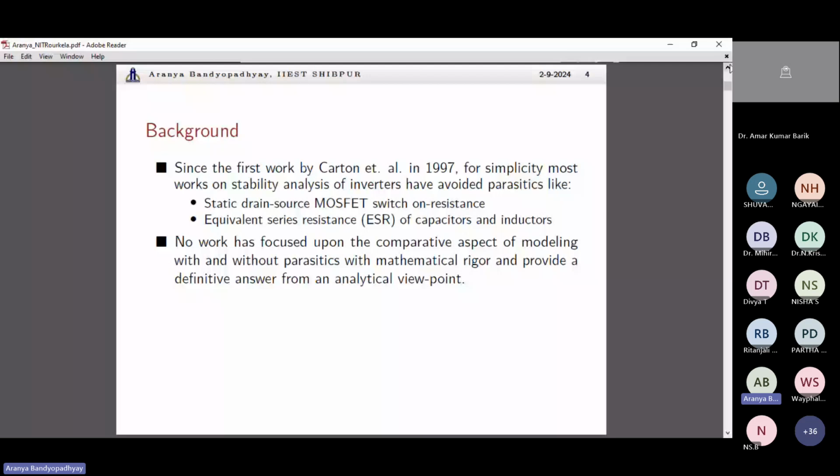That thing is there. And not only that, when you connect the 10 microfarad capacitors in parallel, you are also connecting their ESR, or equivalent series resistance, in parallel. So in effect, you are decreasing the equivalent resistance, which will be much lesser than that of the single 47 microfarad capacitor. But note that a single 10 microfarad capacitor's ESR will always be larger than that of the 47 microfarad capacitor. But since you are paralleling 5 10 microfarad capacitors, you will see a much more reduced equivalent series resistance.